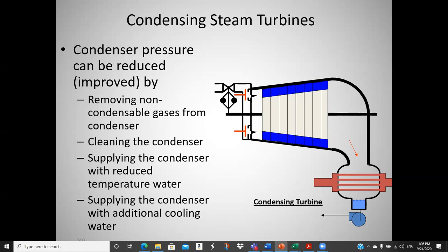Or sometimes, now that last bullet, pumps degrade and your pumps may not be pushing the rated flow. So you can try to take flow measurements on the pumps and make sure that they're up to speed. If they're damaged, then less cooling water, higher back pressure, less power, the way it works.